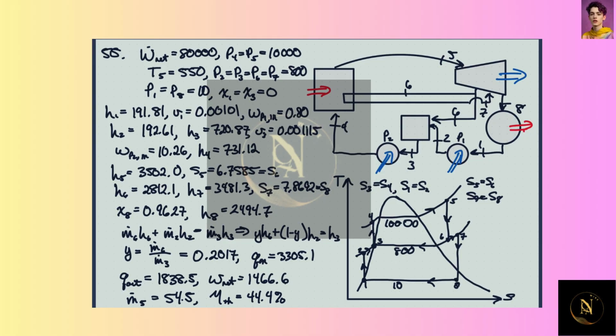And we then boil it and feed it into the turbine. Actually, let me just put a line in here so that it makes things a little bit easier to see. Let's put it right here. So there's like two turbines. We take some of the steam that's coming out of the high pressure turbine, and we heat it again. We throw it back into the boiler.